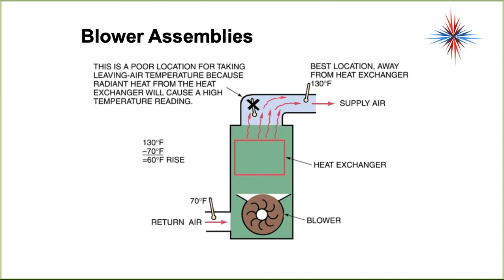Blower assemblies are mounted in the bottom or side of the air handler. Don't worry about anything else on here in terms of temperature rise and stuff like that. We'll talk about that in the future. Right now, I'm more worried about this is a direct drive blower. The return air pulls into it. Supply air pushes out.